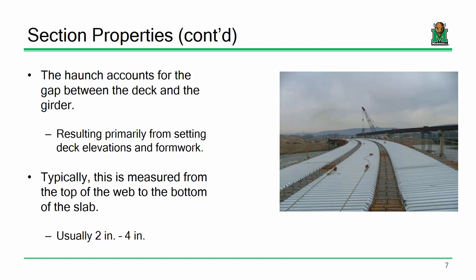So what can happen is you can get failure limits that are a lot lower than you would think. Steel tends to have a yield stress, or at least a pretty common grade for what we use in bridge applications, of 50 KSI, so 50,000 pounds per square inch. But we can have fatigue categories that can fail at 6 KSI or 8 KSI or what have you. So just worth mentioning. Okay.